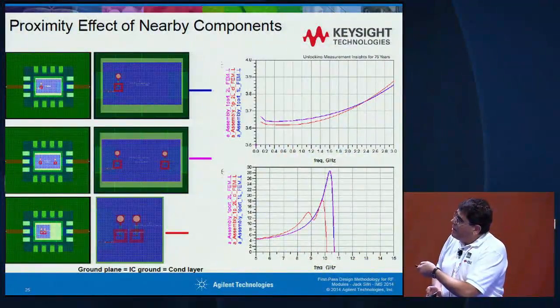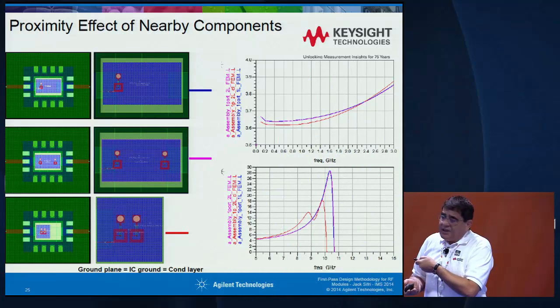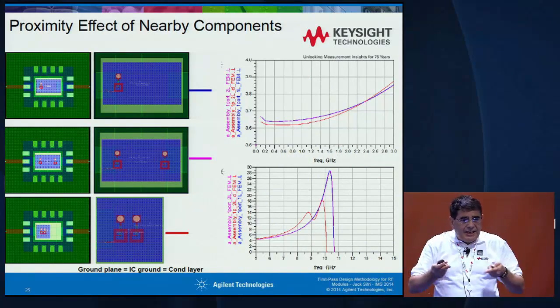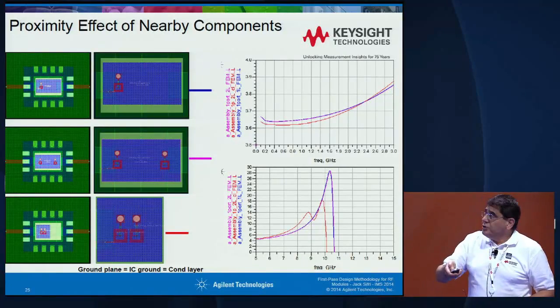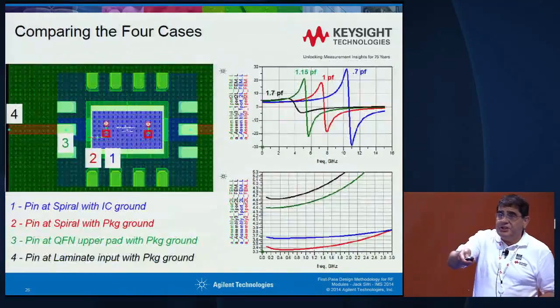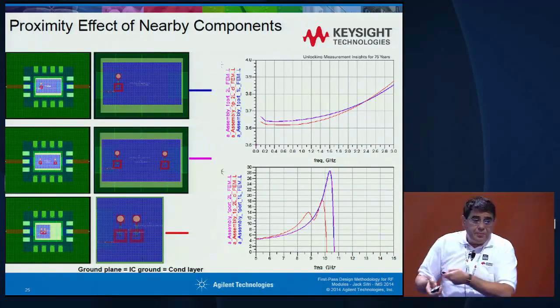Now these double humps, I wanted to understand what is causing them. So what I did, I modeled this inductor. I made a model and I did some simulation of this structure, and I found out, but I don't have time to really show it in this, that basically this double hump comes from capacitive coupling.